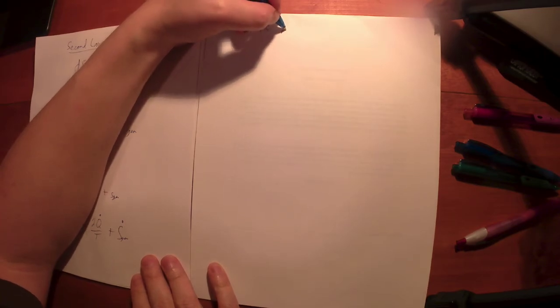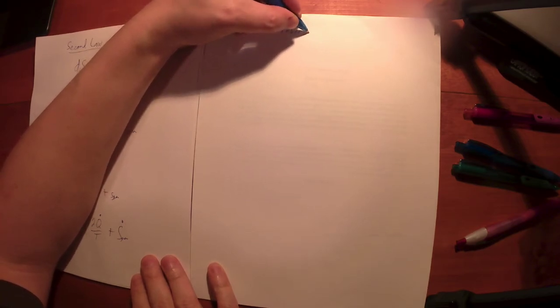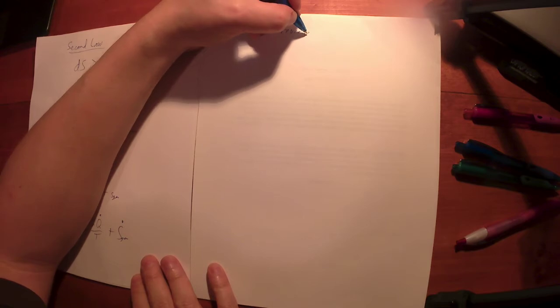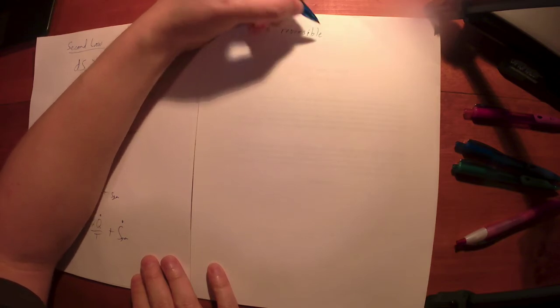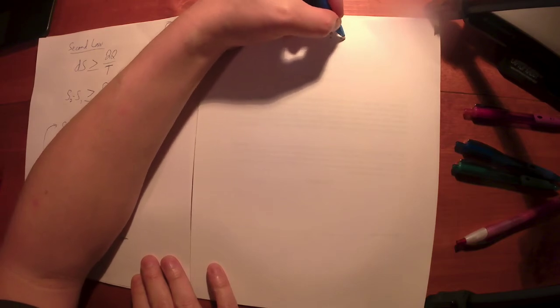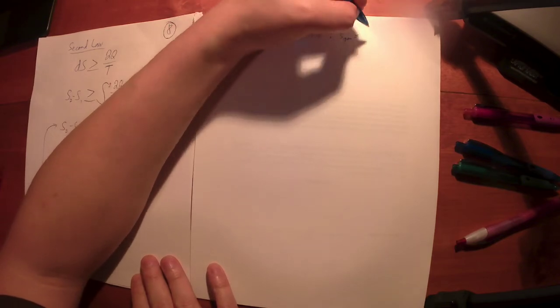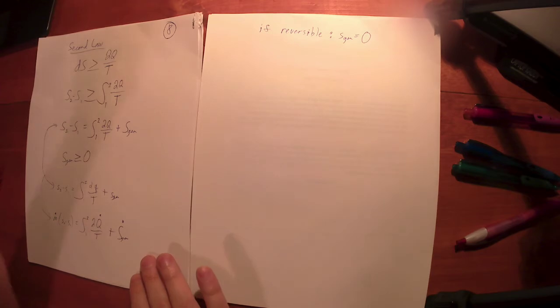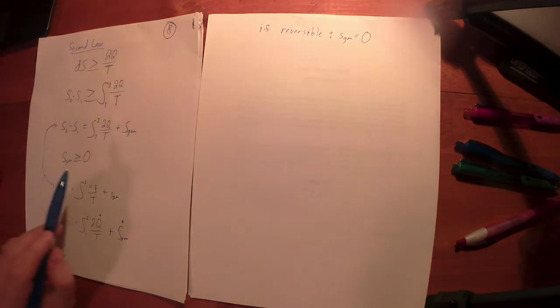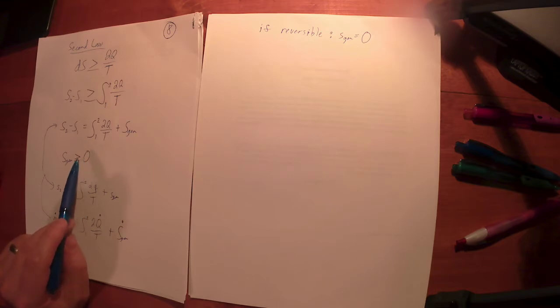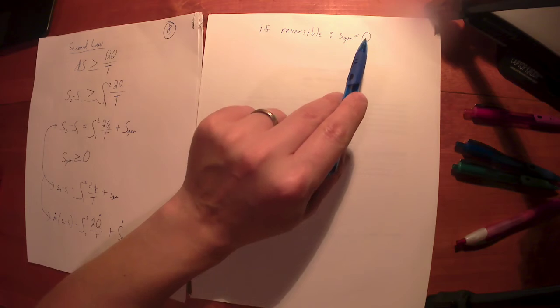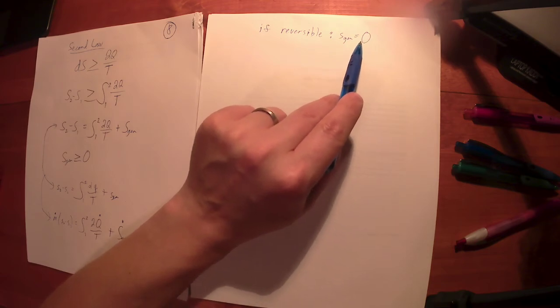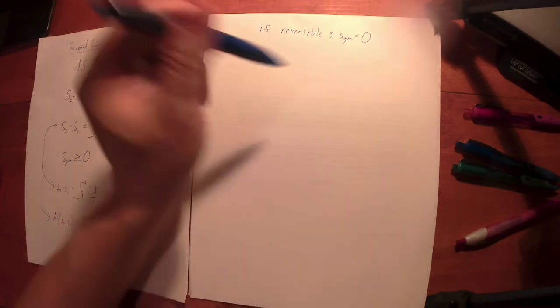If I have something that tells me that I'm dealing with a reversible situation, that's the best case scenario. If something in the problem statement tells me enough that I can assume a reversible situation, we're saying Sgen is always positive or at least 0. The best scenario is when it's 0, when entropy is conserved. We don't generate any new entropy.